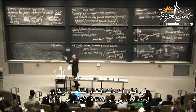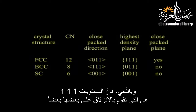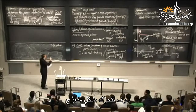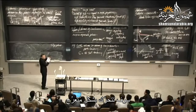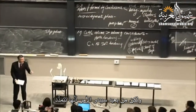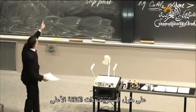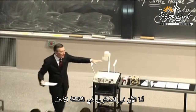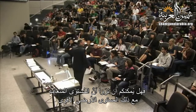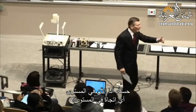So in FCC, the highest density plane is 111. So the 111 planes do the sliding, one over another. And they'll zigzag the way you saw in the Bubble Raft movie. They'll zigzag down, across, across, across, but from a distance it appears as though the thing is elongating. But at the atomic level, it's zigzagging along the close-packed planes. Now I'm in a close-packed plane. By the way, if I have the highest density in the plane of the floor, can you understand that orthogonal to the plane of the floor, I must have the weakest density? All right, now I'm in the plane.